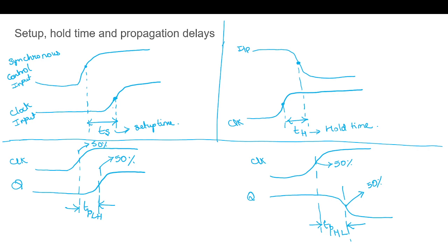If a flip flop is operating at the positive edge, which is the rising edge, the input should be stable for a certain amount of time before this clock edge, and that is called the setup time. After the application of the clock, the input data should again be kept stable for a certain amount of time, and that is called the hold time. Is it clear now? Okay.